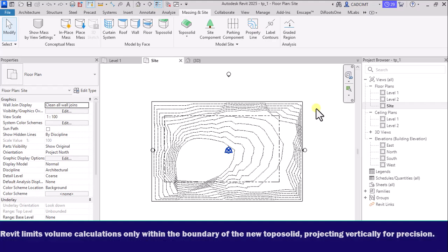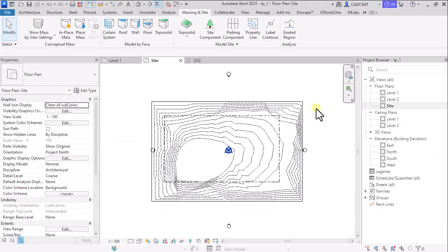After subdivisions, there is another enhancement in 2026, which is the grading enhancement. In grading, the cut and fill volume that was calculated in the previous 2025 version has been updated and the calculation has been made more precise, so that the extra cut or fill that was reported now becomes very accurate, and it will be helpful for excavation analysis. Now let's do a comparison and grade the existing surface.